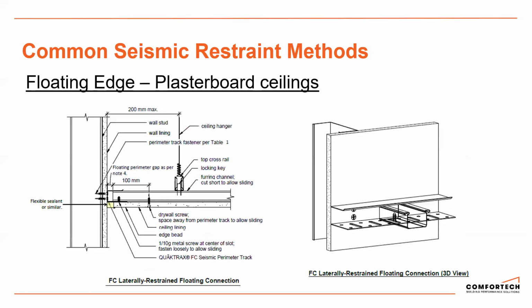The floating edge looks exactly the same from below. You just notice on the right-hand side there that rather than fixing through the holes, we're fixing through the slot into the furring channel, which again allows the furring channel to slide without falling out.